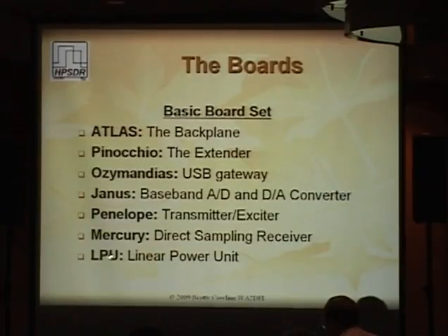LPU, linear power unit, this was kind of a stopgap. There is a switching power supply specified on the HPSDR webpage if you look, but it's been under development for like 3 years. So this was a stopgap power supply, very quick and dirty, just a linear power supply. If you want to heat your shack, this is a good candidate because it produces lots of heat, and you really need to put a fan on it if you're going to run the entire board set in the enclosure. But it's a quick and dirty solution. It plugs right onto the Atlas board, so it's an interim solution until the fancy switcher gets out.